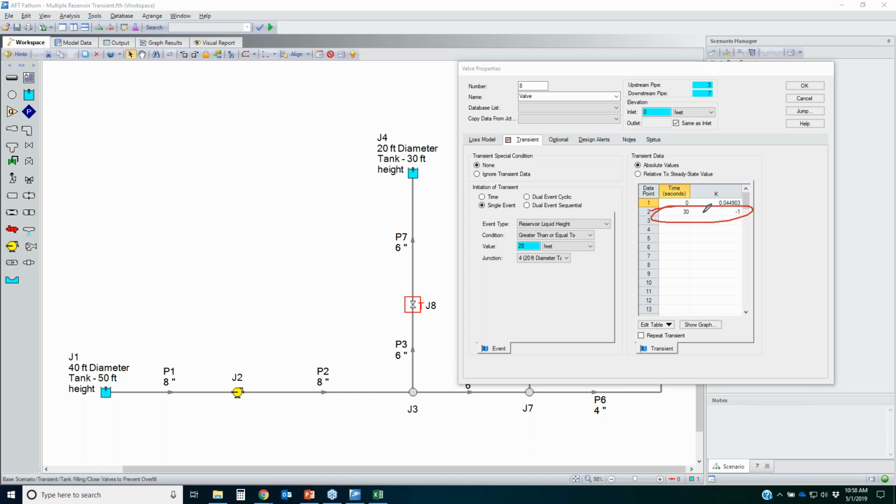I will highlight this again in the next webinar that I do here in the next few weeks. To give you a little prelude of that, when I close this valve, I'm assuming that after this 30-second time period, the next time step, which is 30 seconds away, any pressure waves that have been propagated through the system due to that valve closure have fully dampened out. That way, at my next time step, I essentially would be at a steady state.